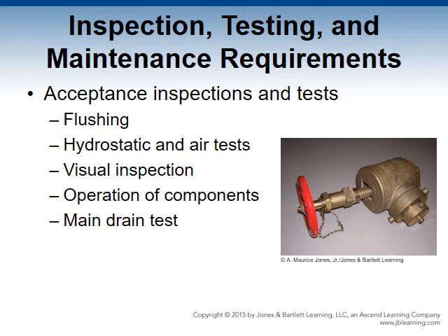First, you have flushing. Before connecting the water supply to a fire sprinkler system, the incoming fire line requires flushing. Once it is determined that the discharge water is safe, the control valve must be fully opened to allow the water to discharge from the pipe and meet one of the following criteria: a rate of 10 feet per second, equal to or higher than the system demand, or the maximum flow rate available to the system under fire conditions. Flushing the line should continue until the water flow is clear.